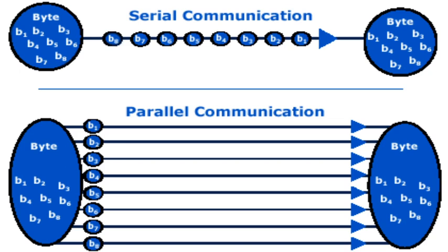So we can see here for serial communication the bits of any 8-bit data, the LSB bit will be transmitted first, and after that next bit. So like that, one bit at a time will be transmitted to that line.